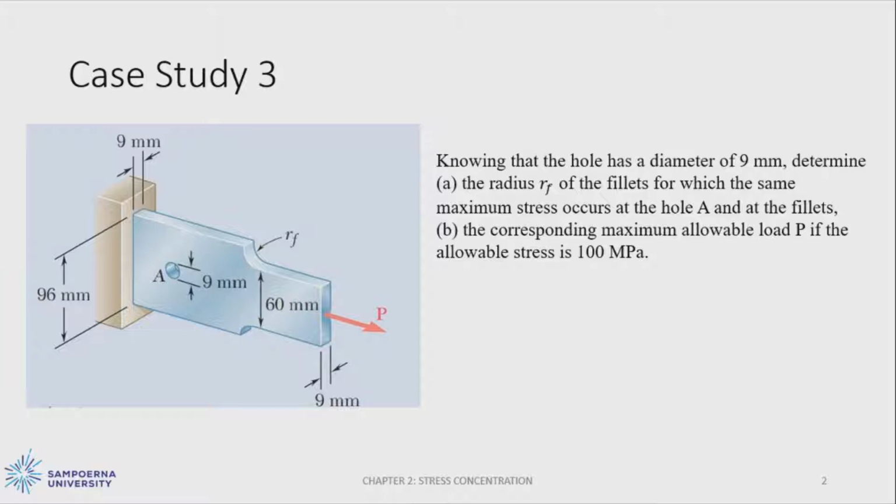need to determine the radius of the fillet for which the same maximum stress occurs at the hole A and at the fillet. And the other task is to determine the corresponding maximum allowable load P if the allowable stress is 100 megapascal.